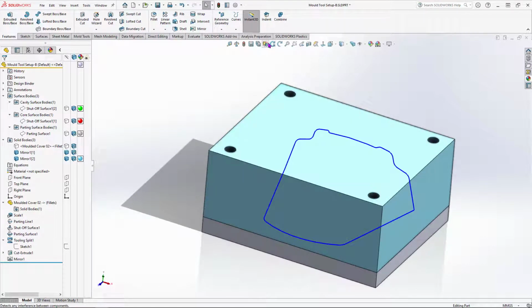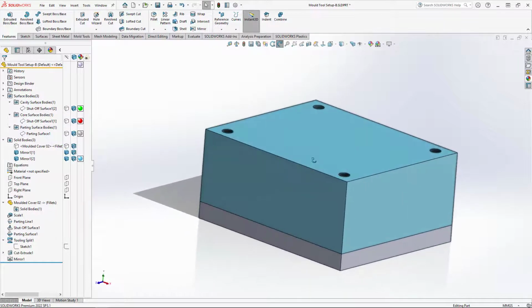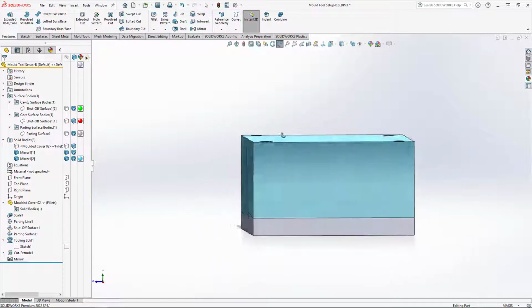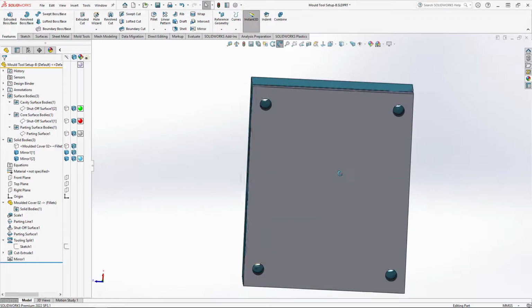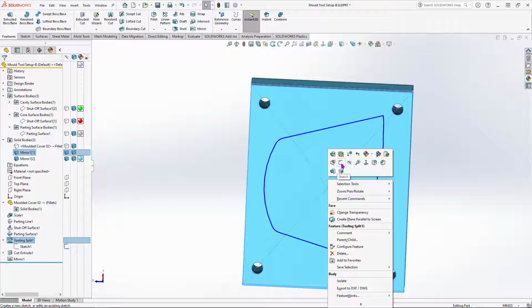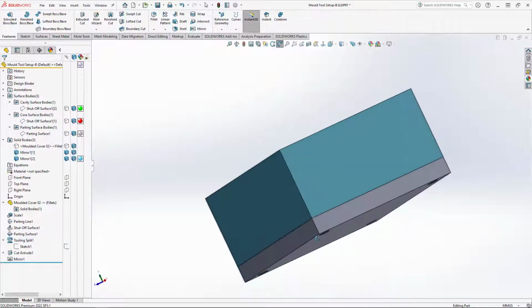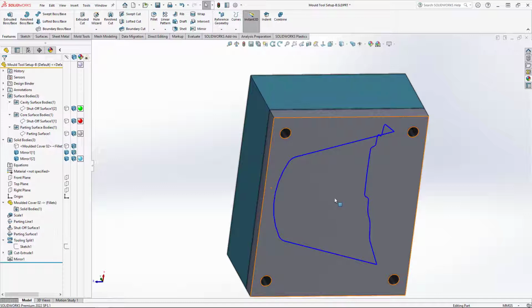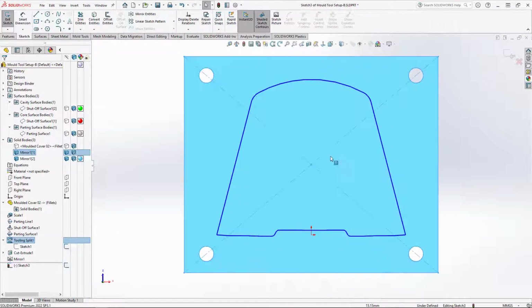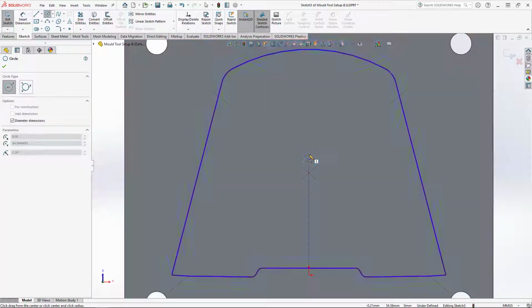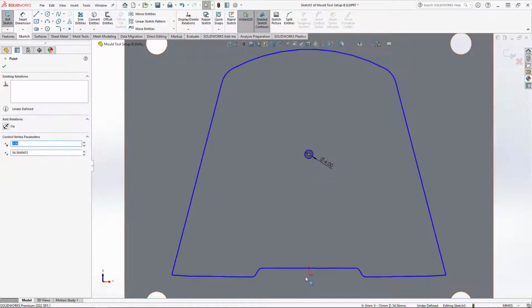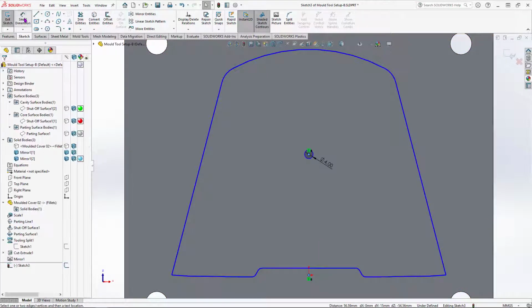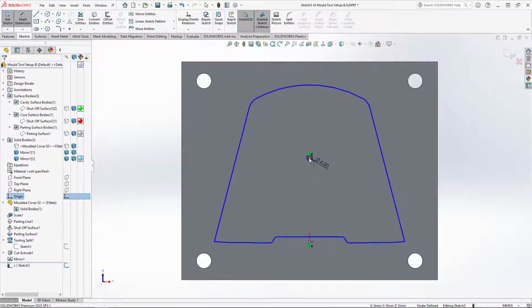If you run your Solidworks plastics analysis, you can then define where the injection point is for your mold tool. So let's imagine there is an injection point somewhere. Let's imagine it's on the bottom surface, which is more likely. So if we could create a sketch and cut straight through to the mold. In fact, let's try that. So let's put an injection point somewhere here. Let's have a 4mm injection point. Make sure that it's central, and then dimension it relative to the origin, let's say.